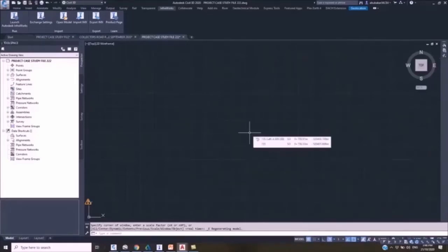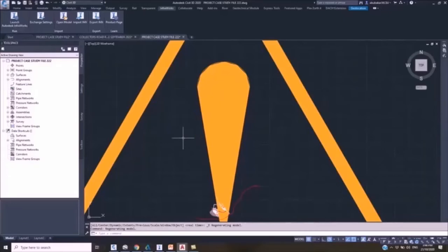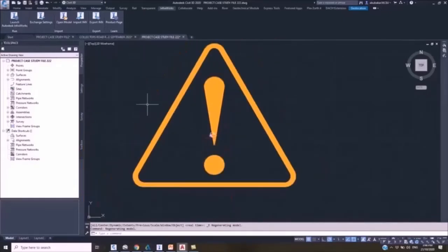So that's what we are seeing in Civil 3D. But by the time we bring in the IMX file, it will give us a surface of the digital terrain model of the map in Civil 3D. Now it has been loaded, but there are issues. These issues come from the condition of those alignments that do not fall in line.